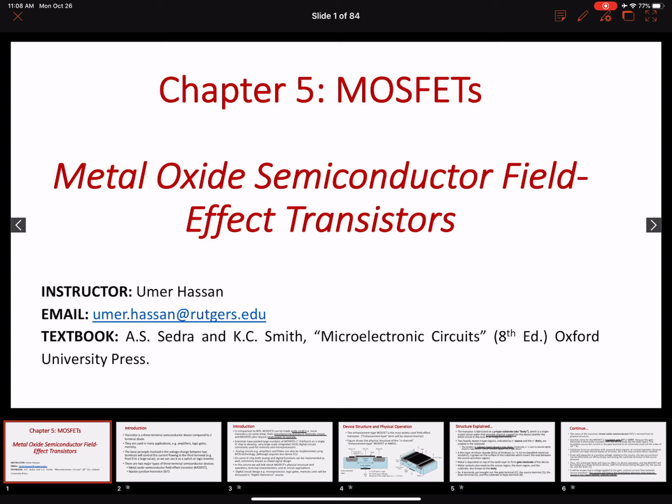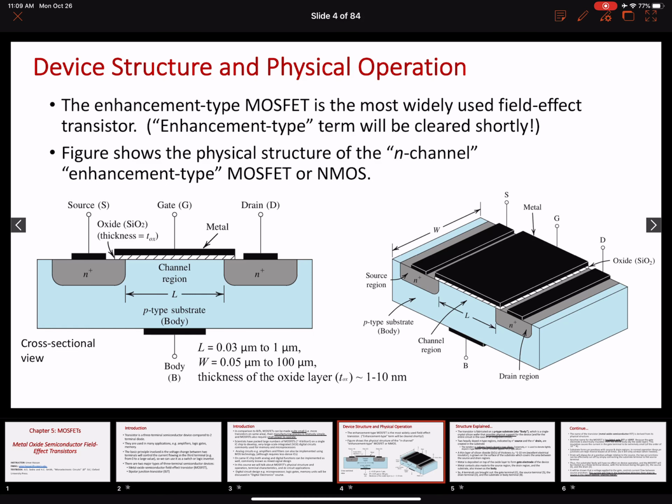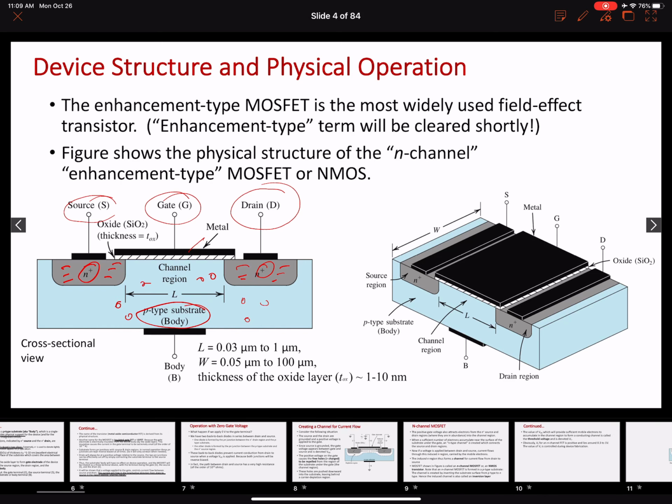Okay, so let me give you a very brief, 3 to 5 minute summary of what we have talked about so far. We started with the structure of the NMOS: source terminal, gate terminal, drain terminal, gate electrode, heavily doped N-type regions for the source and the drain, and P-type body. The majority charge carriers over here will be electrons, and over here it's all filled with holes. So that's the basic structure.